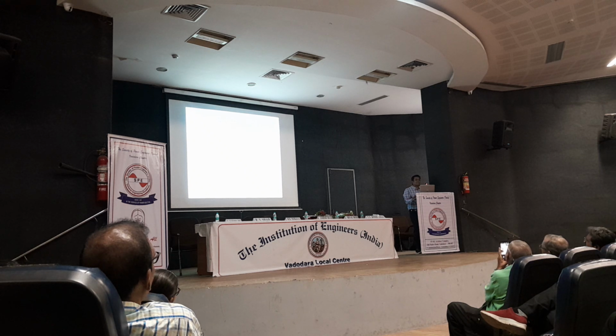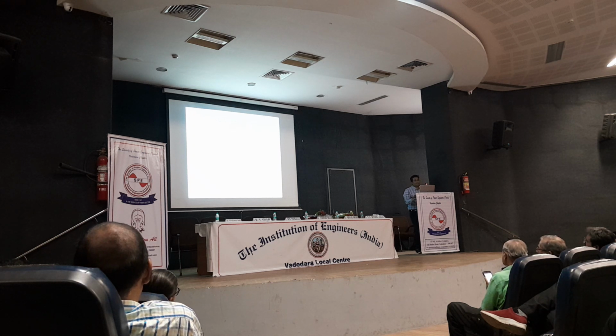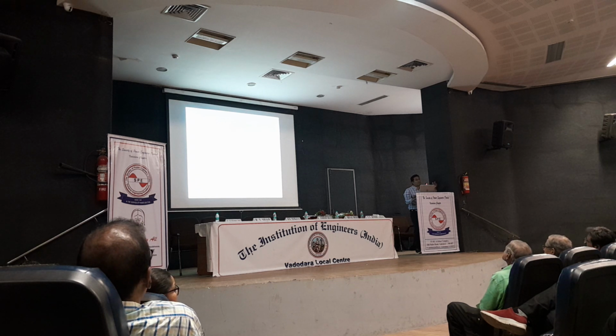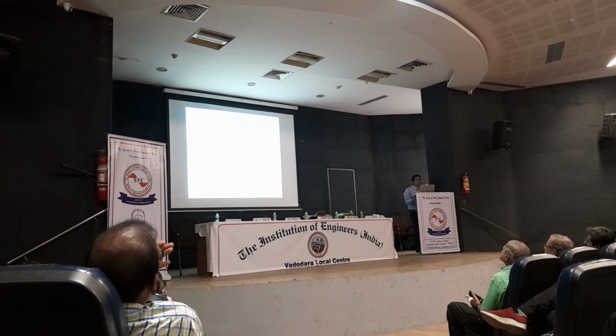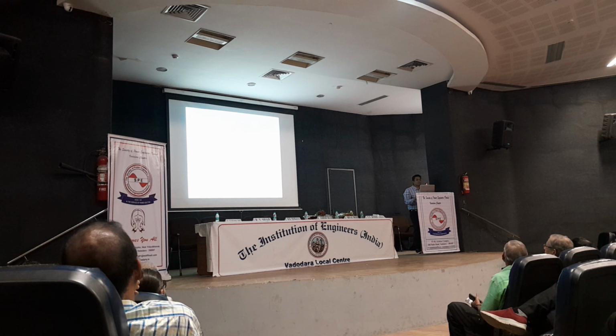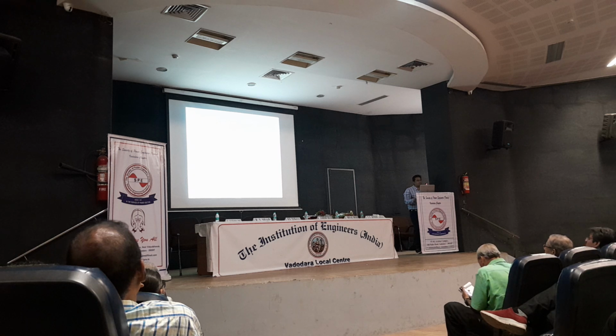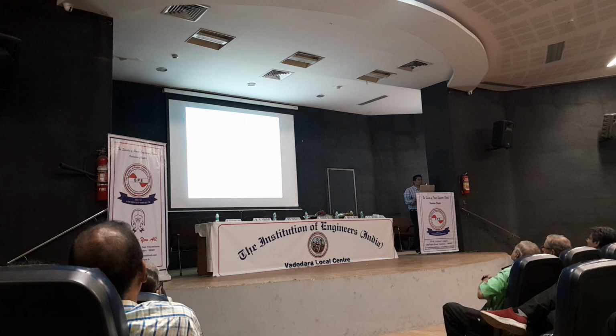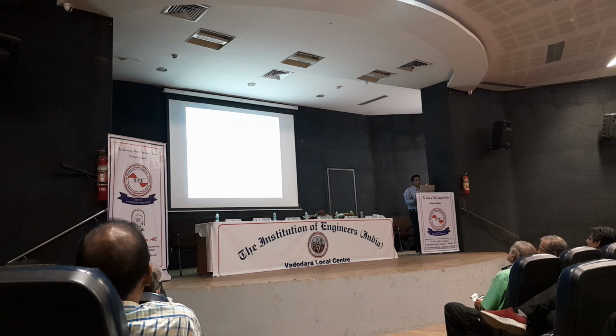So here if you see the results, this 1.2 and 0.8 is contributing to this 2 per unit fault current magnitude. So you can fetch the data in tabular form, and you can interpret how it is 2 per unit. So 1.2 plus 0.8 makes 2 per unit. That information is displayed here in the dialog box. That will be the magnitude of fault current.